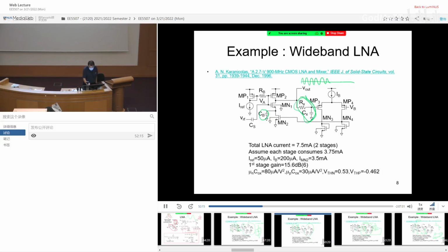After you extract this DC, it's going to be compared with another desired DC, VB. And this output is going to feed back to adjust this amplifier that will affect the final DC point. If you think carefully, if I consider this guy as an amplifier, this is VB, this is after filtering, going to here, and this is actually adjusting this current source.